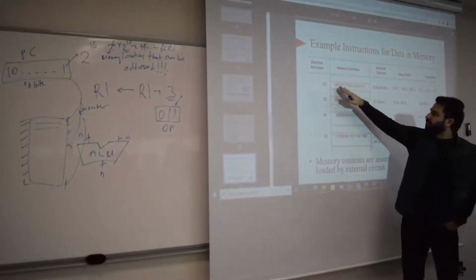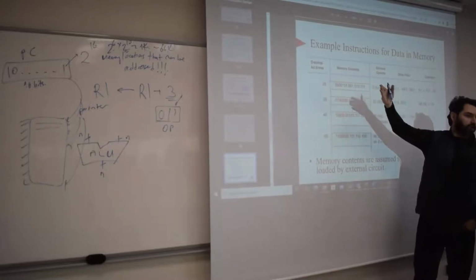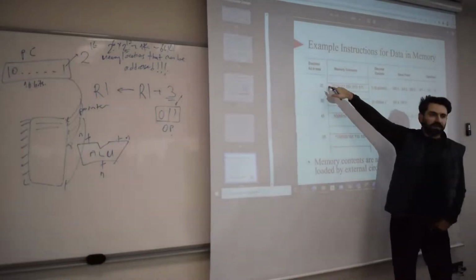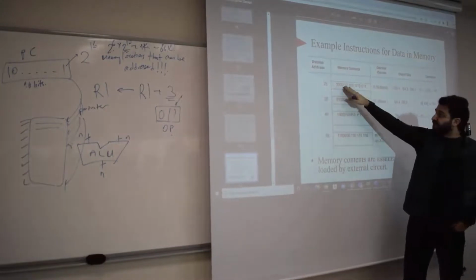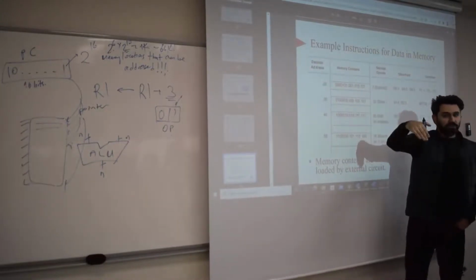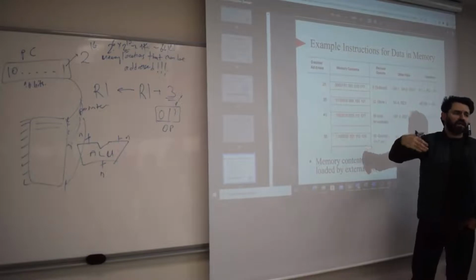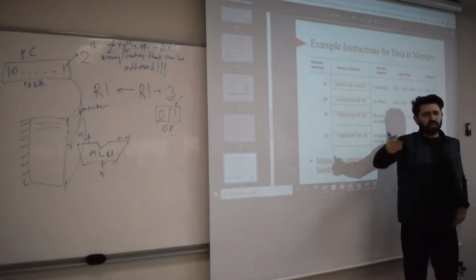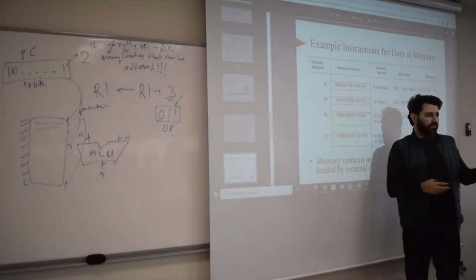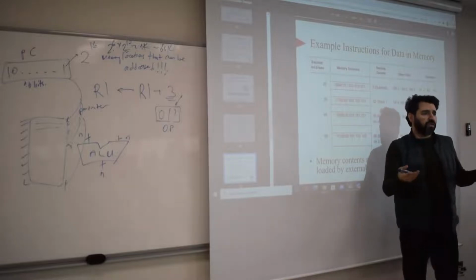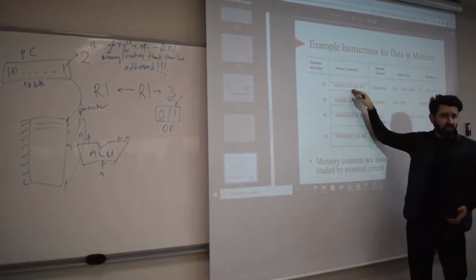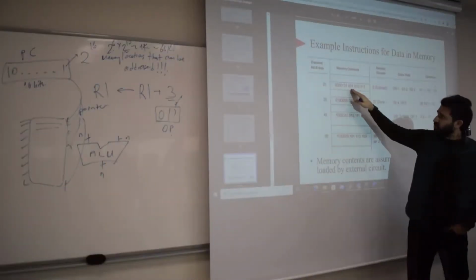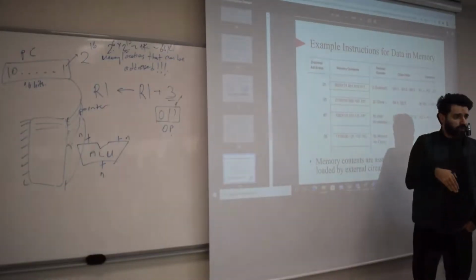If you store this in the instruction memory, and the program counter points to that and reads this, that's called fetching, by the way. It fetches this to the chip register. Most likely there is a register between the chip and the instruction memory that is called the instruction register. That is called instruction fetch. So we fetch this instruction from the instruction memory.